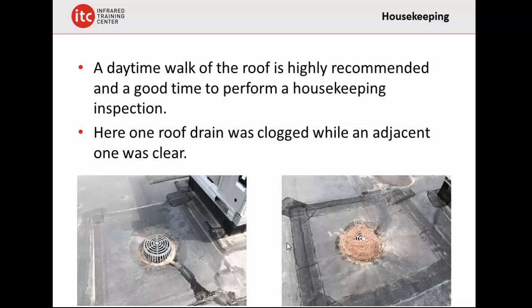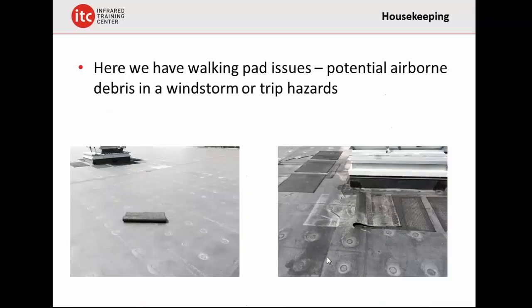It's always a good idea to walk a roof during the daytime before you do your scan, to get a general idea as to housekeeping. Here's a couple of roof drains. Matter of fact, that was on this building here in New Hampshire. This is what we expect our roof drains to be like. This one here was nice and clean. This one was down at one end of the building near some pine trees and was completely clogged up with pine needles. So I told the building maintenance engineer, and they went right up and unclogged it. They were completely unaware of it, but we just had a rainstorm. If you don't unclog these, they can overflow and cause some other issues. So here's a good chance to take a look at the housekeeping on a roof.